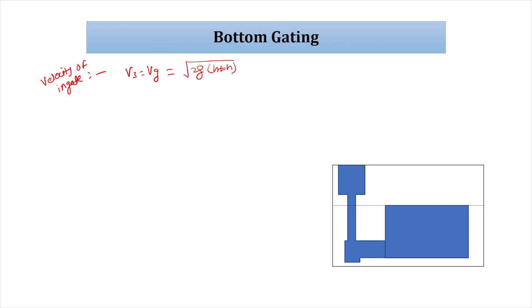Okay. So, we can take a mass balance. We know the inlet flow rate, and we want to fill some volume, that is dV, equal to Am into dH in dt time.